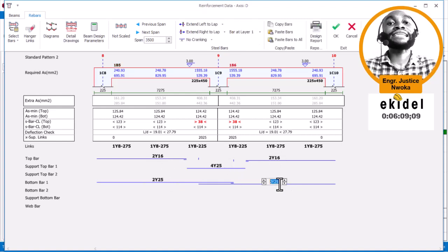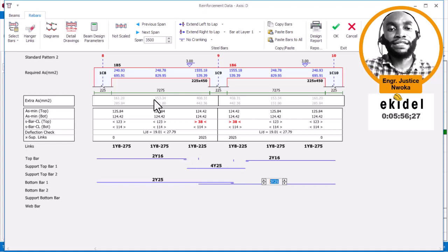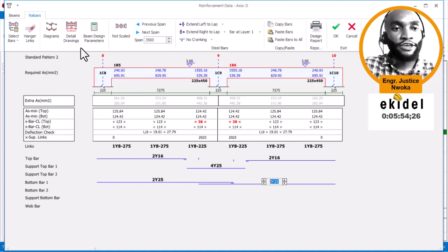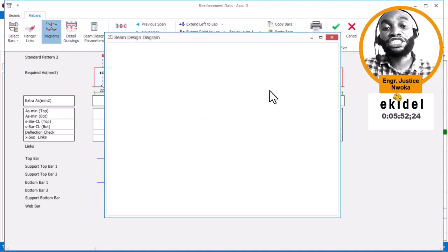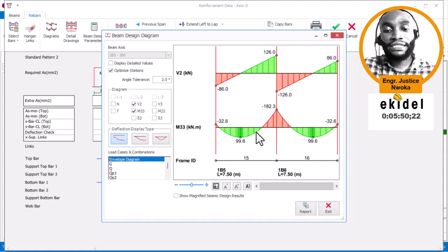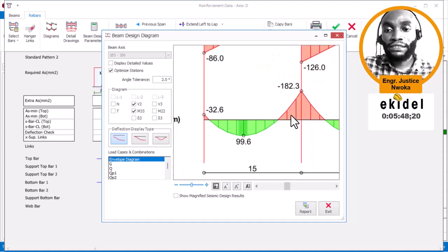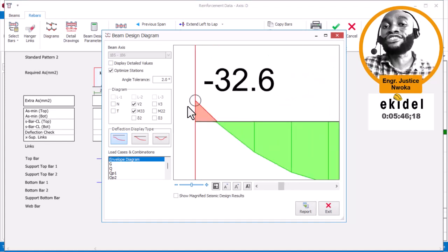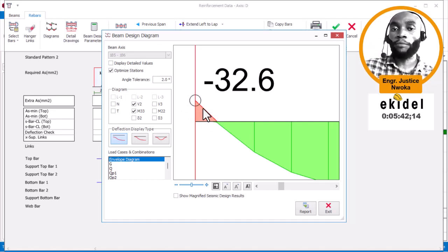You can see now that for a continuous beam, there is not much effect. But you have seen that the main effect happens on the support, which is the column, because of the moments around this region where the moment changes. Let me just show you now. You can see that this place here now has induced moments. So it transferred into the column, the support.